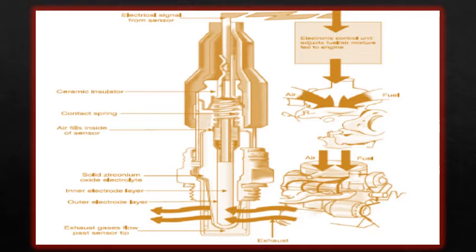Electronic operation of engine valves opens up a further enormous range of possibilities. It would, for instance, allow the driver to change the characteristics of an engine at will. At the flicking of a switch, he could change the car from a highly tuned sports car to an economical slugger with plenty of pulling power, simply by altering the timing and duration of valve opening. Or he could shut off the valves altogether, turning the engine into an air compressor for efficient engine braking.